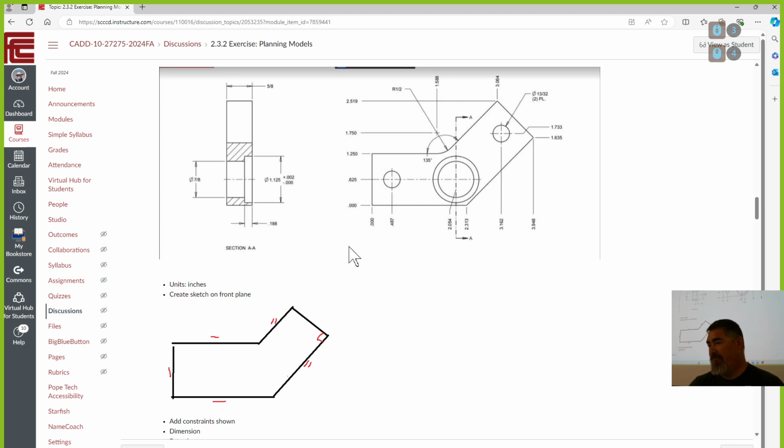And then dimension it. Actually, this probably isn't how I would dimension it. I wouldn't have used ordinate on this part, but this is what we were given. We might redraw this one again in AutoCAD, so that way you can see how having it ordinate does help with some things. Like for guys in the shop, they like this because they know, okay, come from here, come over, come up. That's where that center is. They don't have to measure in from the side or anything. If it's on a manual, if it's on CNC, then it doesn't matter. You can draw it either way.